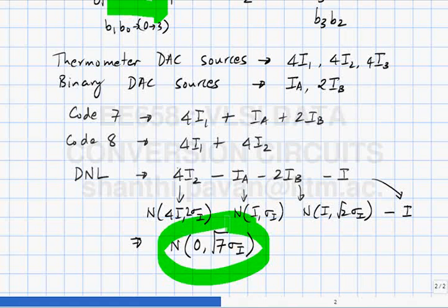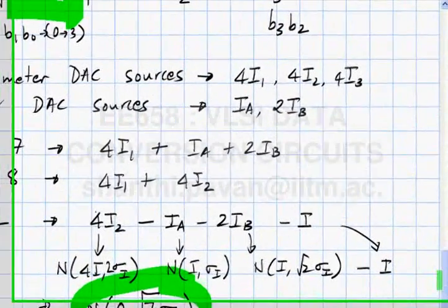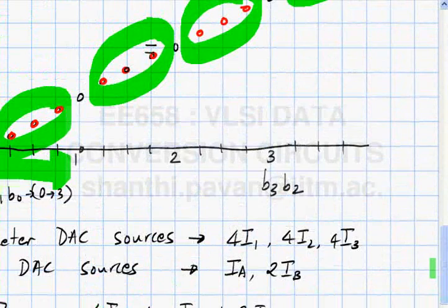The size of the decoding logic has also gone up, alright. However, when compared to a pure binary DAC, how much has the size of the decoding logic gone up by? A factor of 4, correct? Because if you assume that the complexity of a simple binary DAC is just 1, you now have to generate 4 lines from the 2-bit code. The 2 MSBs will be generating 4 lines, correct?